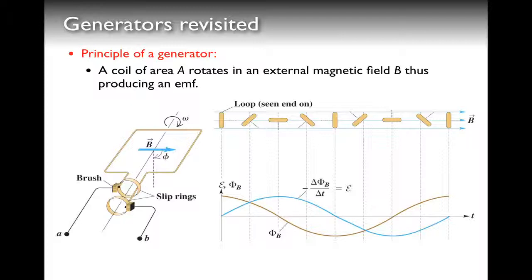And then the hoop starts rotating, and now you have to basically see what happens at the point where the flux is zero, meaning that the hoop is perfectly horizontal in the field. The flux is of course zero because it goes like the cosine of the angle. But if we now trace this change in the flux, which corresponds to the change in flux by time, which means the EMF, you see that it's going to be maximal where the curve for the flux has the biggest change in slope, and this is around where phi equals 0, in other words, the derivative of the cosine function. And you see very nicely that the induced EMF is going to be minus d phi over dt, which gives you a sine function.